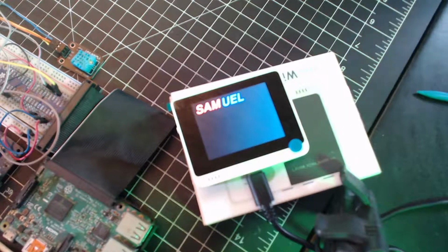Or you can also use what we call the Serial Peripheral Interface, which is just a way that microcontrollers communicate with small peripherals like shift registers, sensors, and SD cards. These are the three ways you can interface: analog, digital, I2C, or SPI. So let's take a look at the analog.